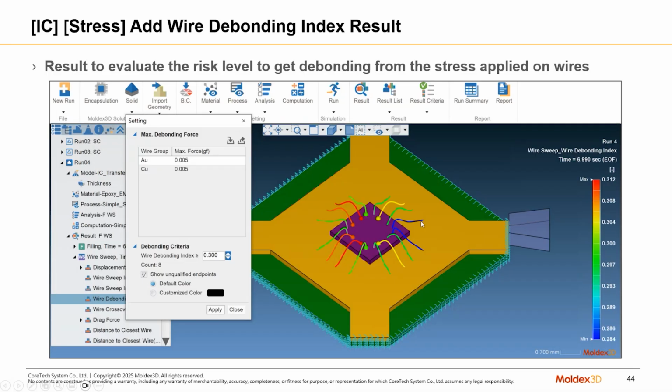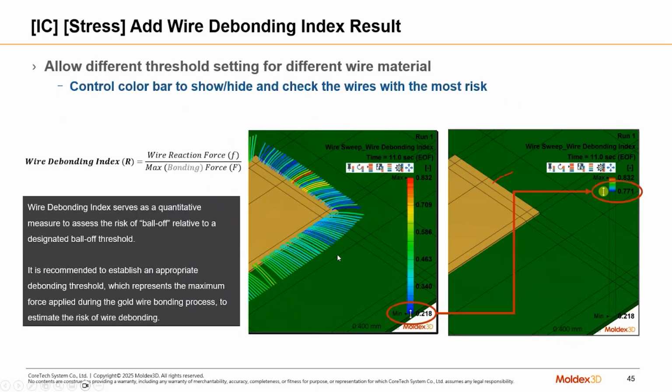And so this wire sweep analysis has always been something that we could run, but we really had to go through Rhino or some other meshing software to get this mesh. Now that we have a nice methodology for creating a structure mesh in Moldex3D since 2024, we can now support this wire sweep type of analysis. All right, and here's just another look at what that wire sweep is going to look like. So the pressure of the melt coming across these wires is going to dictate how likely it is for that wire to be swept away or broken from the surface it's connected to.